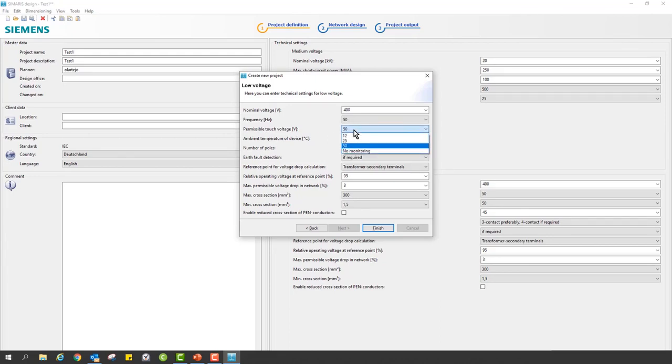Of course, there are some restricted applications when you might be wet or there might be high humidity. This also takes into account the impedance of your body. 90 to 95% of all applications have been calculated and work with this 50 volts that we have here. But of course, if you need to change it to 25, as in 24 volts DC, or 12 volts, we can actually do that. We will leave it at 50. The standard allows us to do it like this.